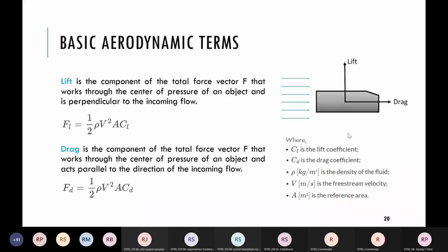We can compare it with the center of gravity. In aerodynamics, it's called center of pressure. At the center of pressure, all the aerodynamic moments are zero. With the change in wind speed and in orientation of a body, the center of pressure changes, unlike the center of gravity. There is another term called aerodynamic center, but that is a talk for another day.